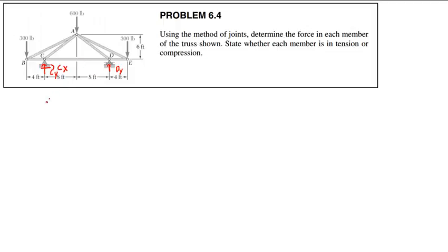Now, just looking at this, do y'all notice something peculiar or particular about this truss? Something that might be useful? It's symmetrical, yes. It is perfectly symmetrical, which means if our dimensions, our members, and all our loadings are symmetrical, then we can use arguments based on symmetry. We can only use arguments of symmetry if both the geometry of the truss and the loadings on the truss are symmetric. But as long as everything is split 100% right down the middle, everything has to be symmetric.